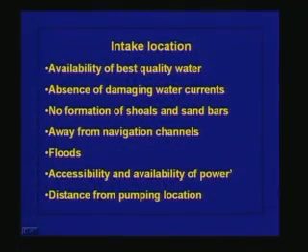Again, the location of the intake structures also depends upon what kind of floods occur in the river and what kind of flood damage could come on the intake structures. This is very, very important. As we have seen earlier, we may locate the intake structure right in the river, or we can locate it a little far away from the river.